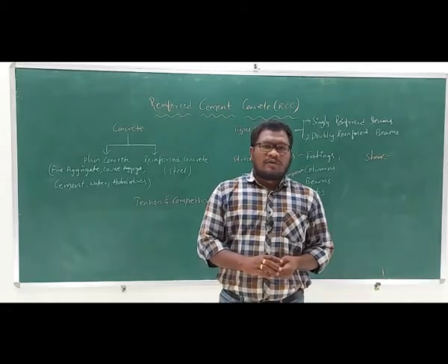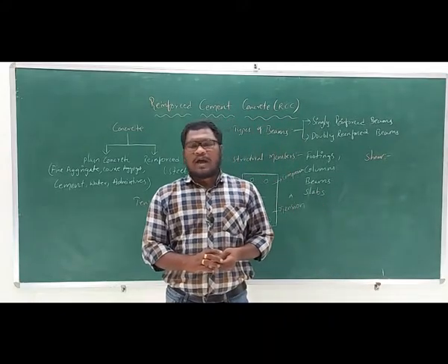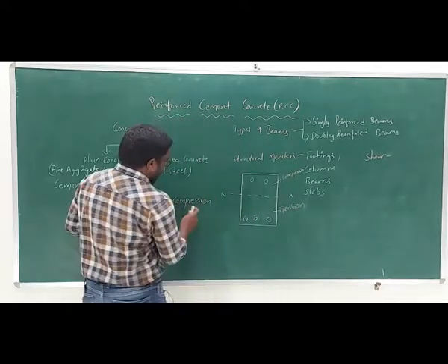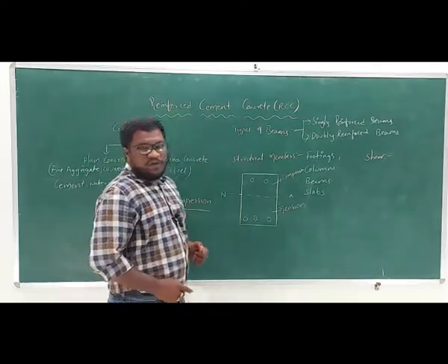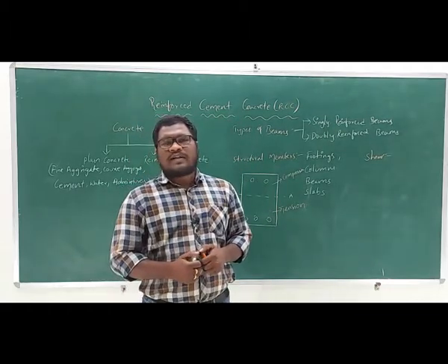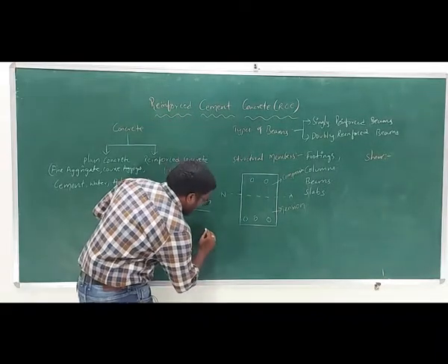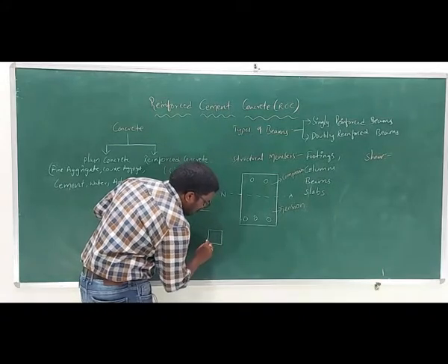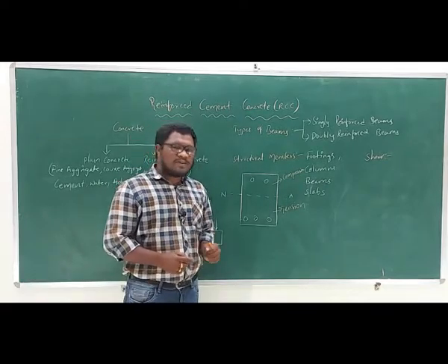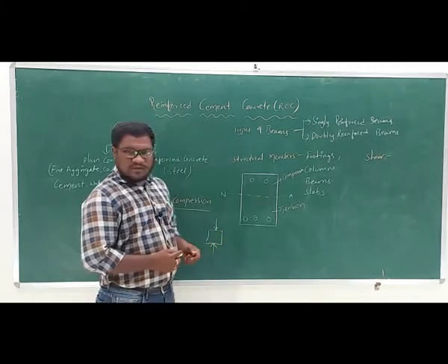The concrete which is manufactured, after attaining its final strength, is good in compression and weak in tension. When compressive forces are acting on the concrete, it can withstand them, but when tensile forces are acting, the concrete may fail. For example, if it is a concrete block and I apply the load on two opposite faces of the block, it can resist to some extent and no deformation occurs.